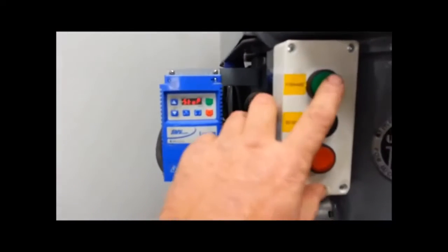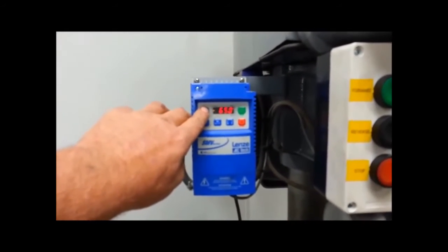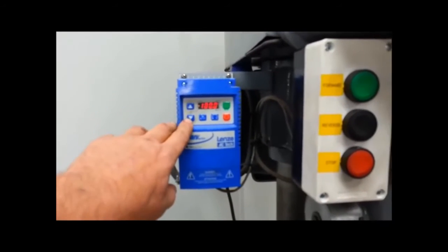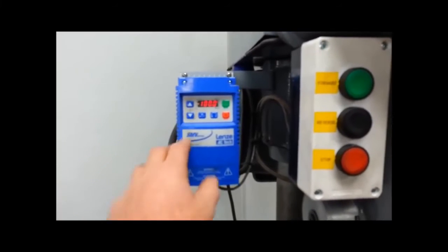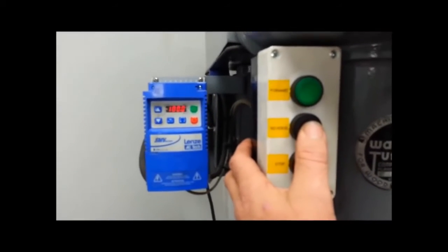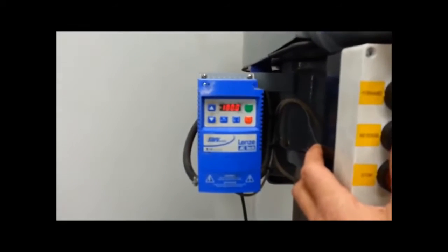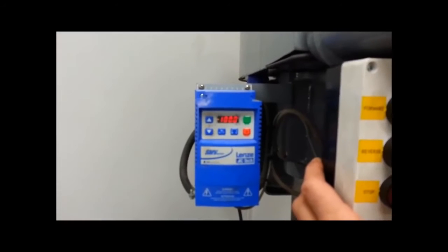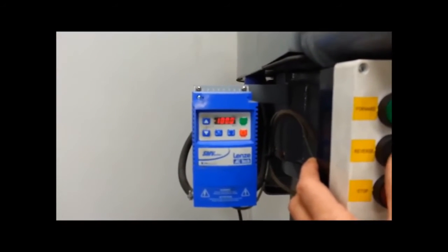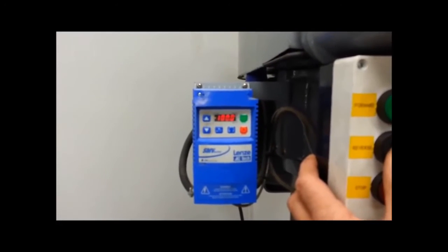Here's another example. We ramped up to a start, and now I'm going to run it all the way to 100 hertz, and there she is running at 100 hertz, and I'm just going to hit the reverse button. Typically this is a big no-no on a 3-phase machine that doesn't have a VFD, but you're going to see the display go into DEC, which means decelerate, which also means within the unit it's using the DC bus to brake the motor.